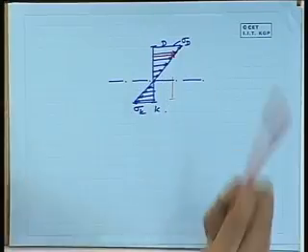So only where you expect, normally in very large tankers where the depth is very high, one can go for high tensile steel in the deck and keel construction, but the remaining part of the hull and internal arrangement can still continue to be mild steel.